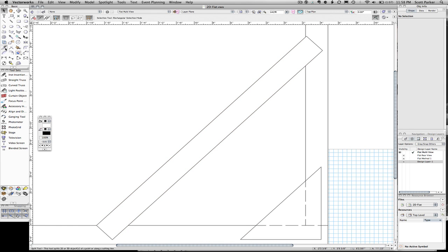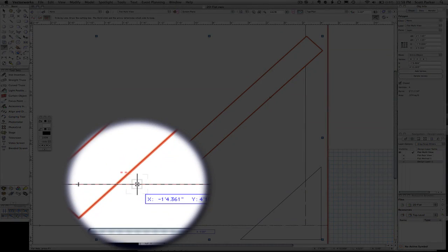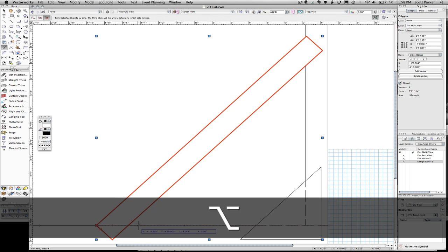We're going to select this object, use our Split tool, click on this corner, draw a line this way, and in order to only split our single object that we want, we're going to press the Alt or Option key. This command executes our desired split upon just the selected item.